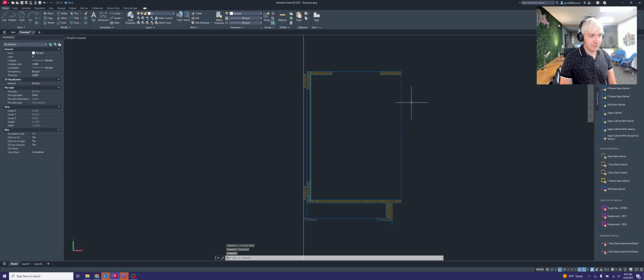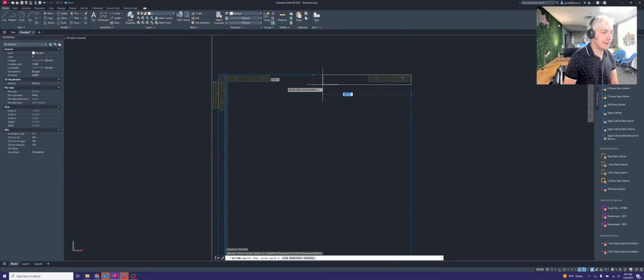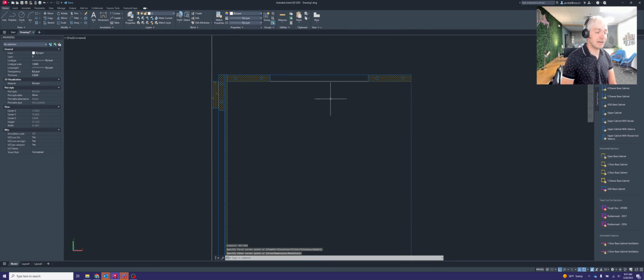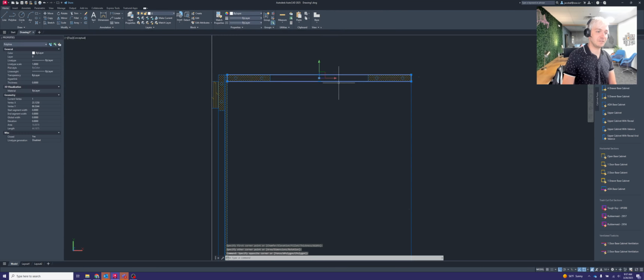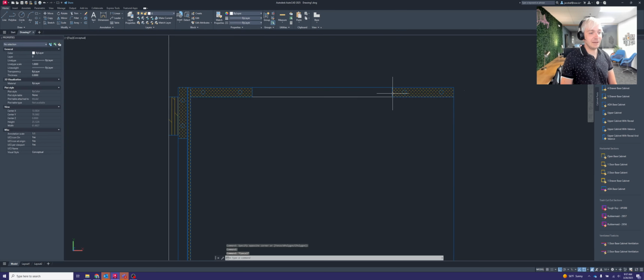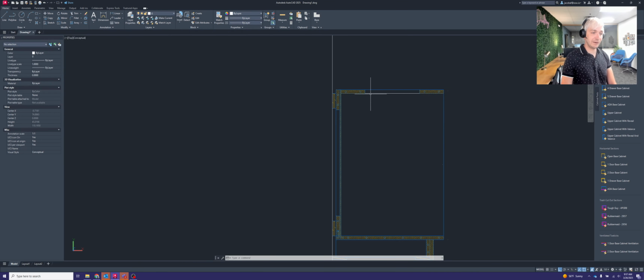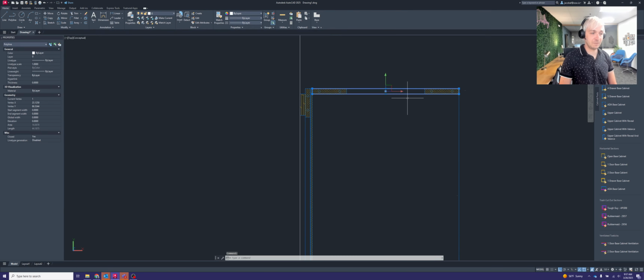Now, if you have an open cabinet, you're going to also need to make what is called a full top. So open cabinets and tall cabinets will require a full top. Currently, the block does not have that built into it, but a full top would mean that instead of having 2 rails up here, you're going to have one entire top that's made out of a singular panel instead of 2 individual rails. So this whole top is going to span from front to back of the cabinet.